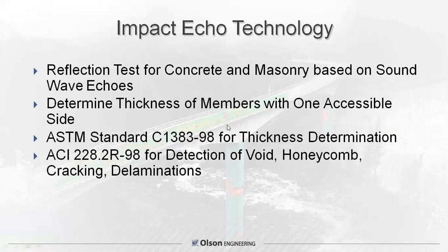One advantage of it, again, you only need access to one side. There is an ASTM standard, but it's really primarily for thickness determination, not for forensic applications. ACI 228 is probably a better reference for impact echo for forensic applications.